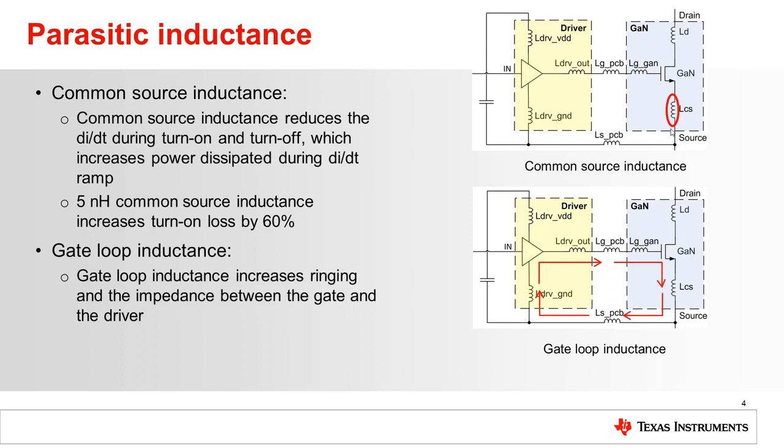Here, since TI-GaN integrates the driver with the FET, the common source inductance is almost eliminated, which ensures the best device performance and is one less thing you need to worry about during layout.